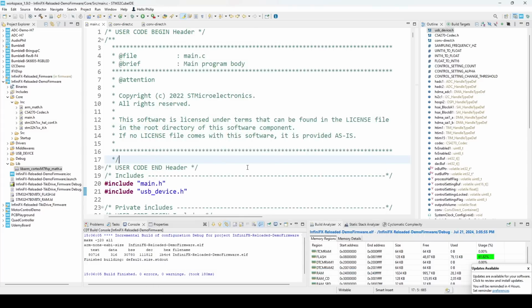So now we're pretty much ready to implement the FIR filter with the help of these CMSIS DSP libraries, which are optimized for these Cortex microcontrollers, and we do get quite a bit of a speed boost compared to writing our own FIR filter implementation.